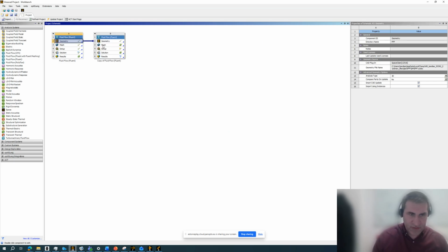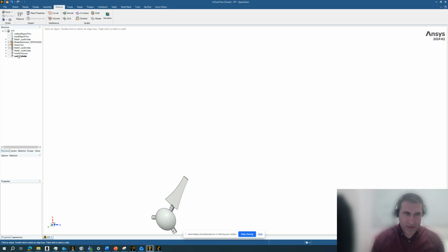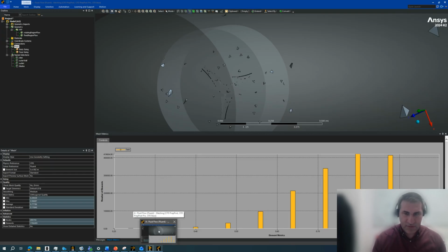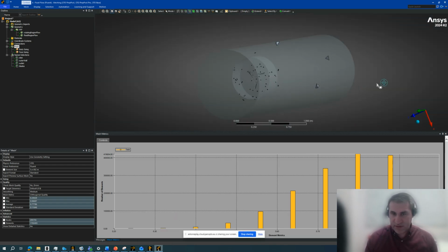I can go to the mesh and refine the mesh, for example, 5 million, 10 million. So I can open the mesh, refine it, set up the simulation again, run the simulation and compare my results with the previous one. And also I may try to extend the region, I mean, make the outer region bigger, especially in the back, to make sure that the region is not affecting my simulation.